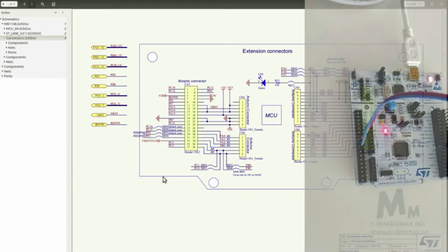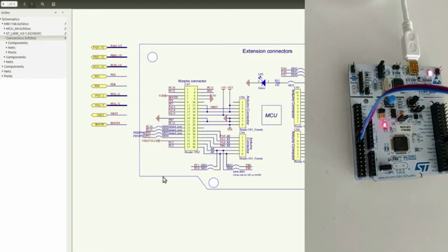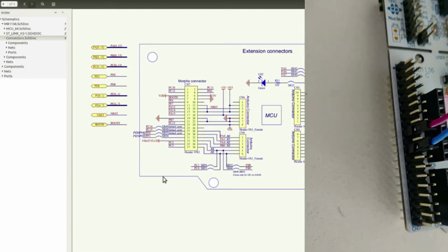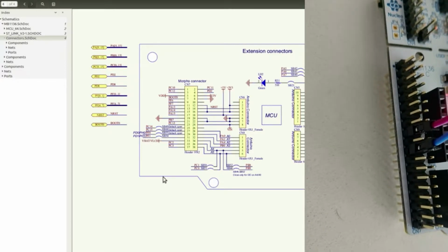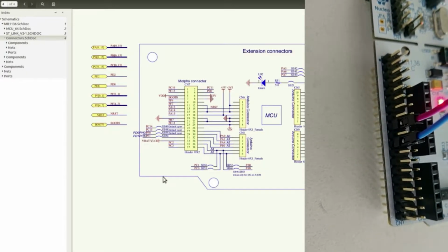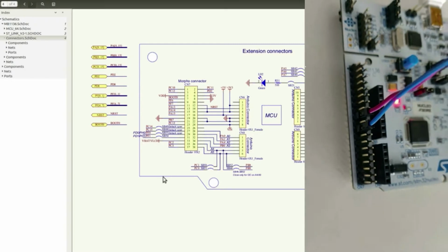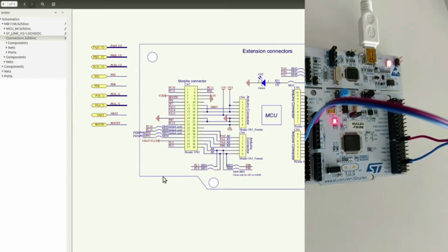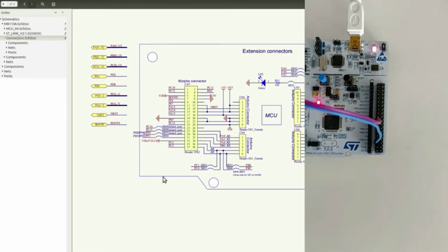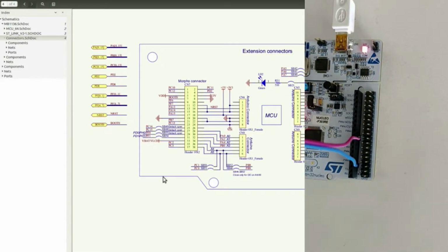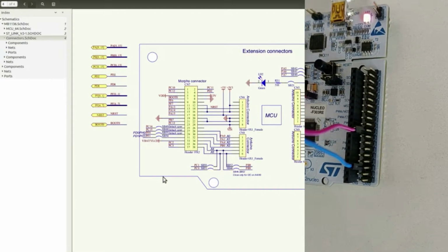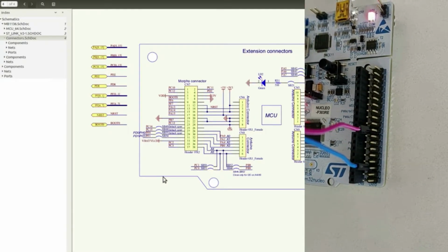On the hardware side, what you need is the Nucleo board that is hosting an STM32 microcontroller. You can choose whatever Nucleo platform you want, or even discovery platforms actually. It doesn't matter, as long as the microcontroller that you're using has two I2C peripherals on it. In my case, I'm using the Nucleo F303RE board. Most Nucleo boards have a debugger and programmer on the board itself from ST, called ST-Link, which lets you debug the program and program the microcontroller.